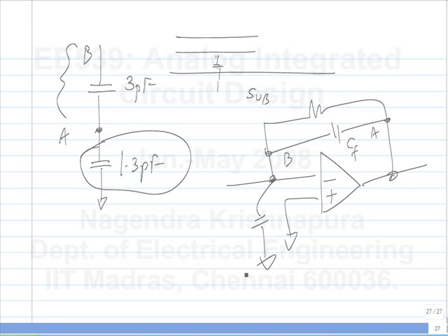Okay. So although a capacitor by itself is a symmetrical device, in this case from one side you get an extra capacitor. You should make sure that that extra is driven from the output. Because the op-amp output has a relatively low impedance, it doesn't matter. But if you make it the other way around, if the parasitic appears on this side, then you already had some parasitic capacitance, you wanted to compensate that, but now you have increased your parasitic capacitance. Okay.